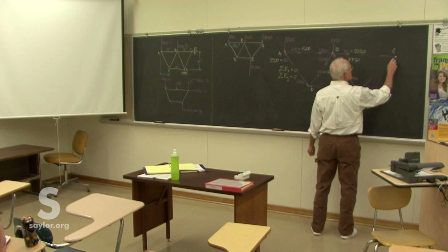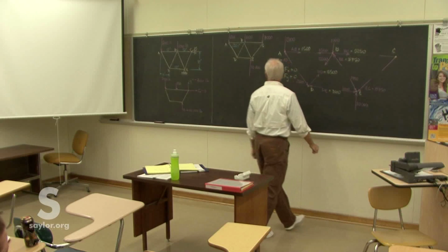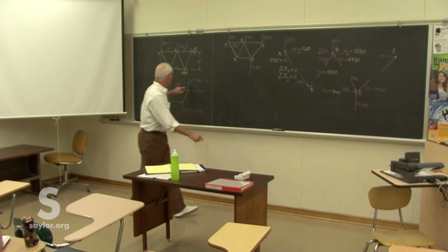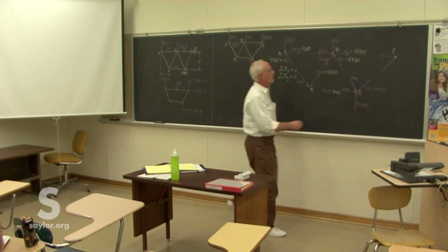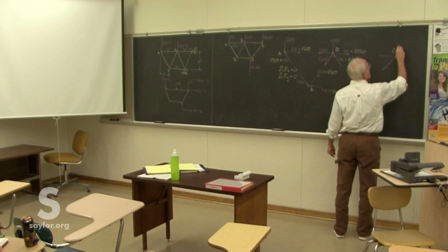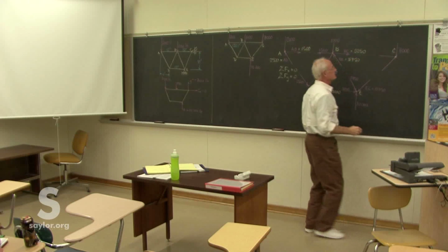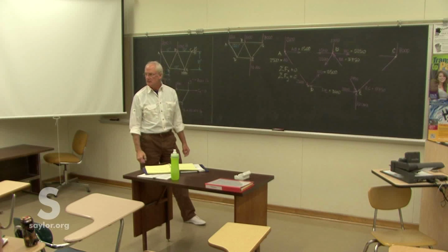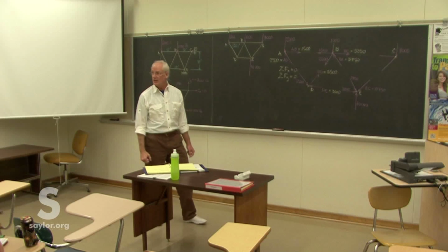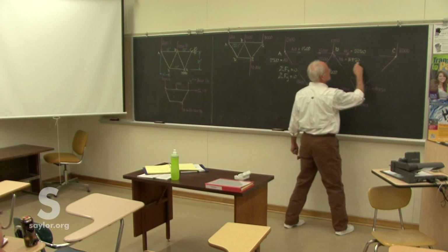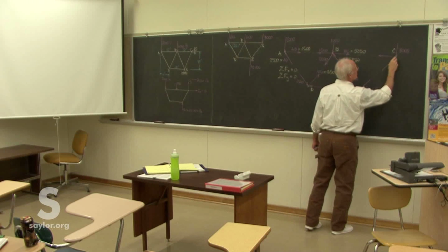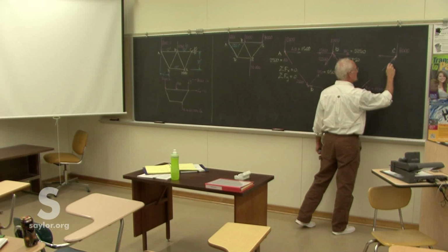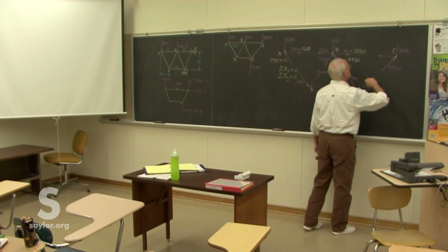Let's see, we know there's a force there. What else do we know? We know the reaction force. We know we've got it backwards, so we'll go ahead and turn it around now. We know it's 7,000. What about the other 2? 15 seconds was generous. You could have done it that quick because we've got these forces already. There's nothing left to do. We're done. So that one goes down, this one must go up, and we already know their magnitude, their direction,